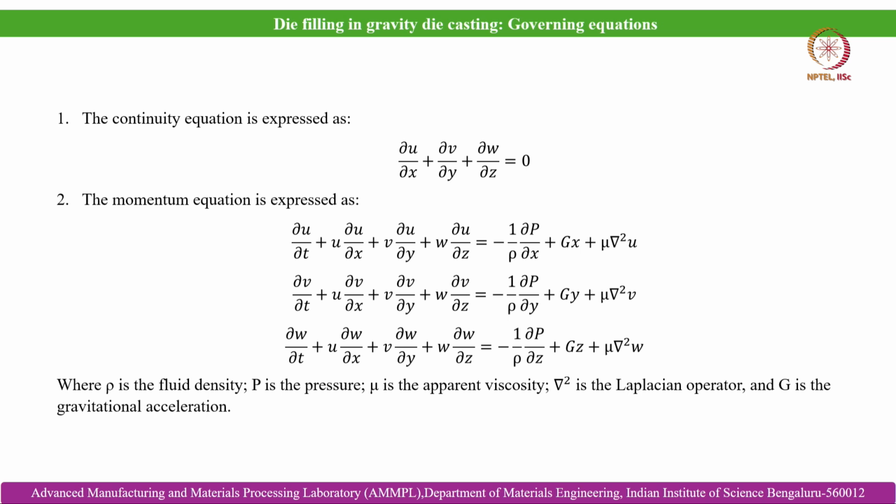That is why we need to take care of these aspects, and out of these casting defects, which largely originate from gas absorption and also from shrinkage, that can be nullified. Shrinkage we have discussed earlier, how we can design the riser so that we can optimize the shrinkage porosity, and how we can quantify and mitigate the gas porosity, that we have also discussed. And we will now discuss, with the help of a case study, die filling of gravity casting.